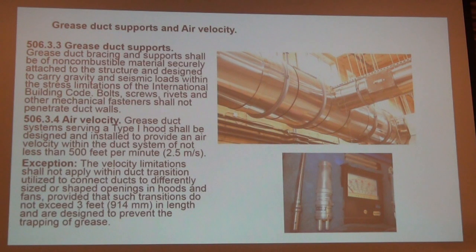How about boilers? Boilers. Oil-fired boilers would require it. How about gas-fired boilers? Gas-fired boilers have a spill switch on them. A stack switch. So they do have it, just the oil doesn't have it. Oil doesn't have it.